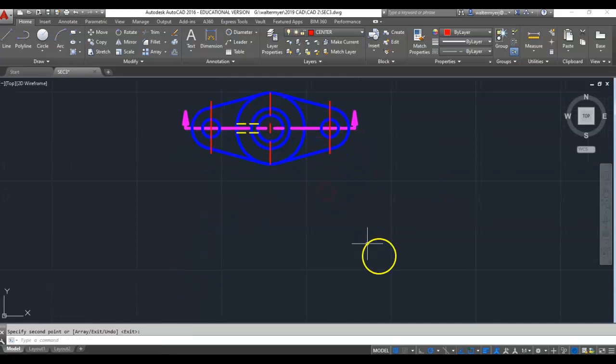Alright, so top all done. Section view in the front now. I'm going to bring the outside edge down, other side. Alright, this part, the flange on the sides is 3/8 thick. So I bring it over. The 2-inch circle, I'm going to bring down, and then it is going to come up 1 1/8 inch. 2 over, because that lines up with the other side. And down.